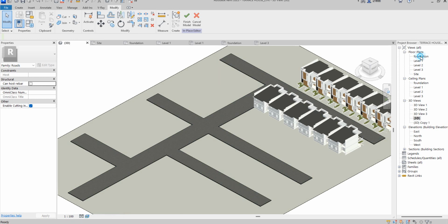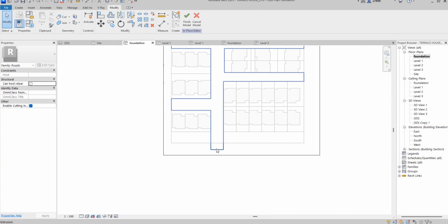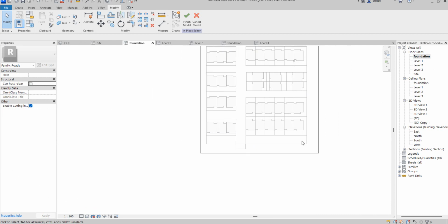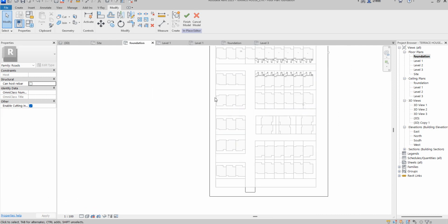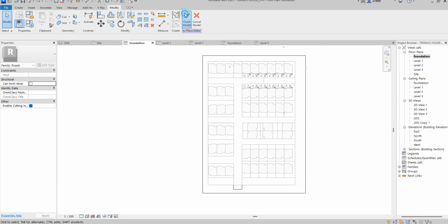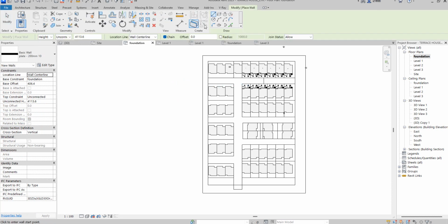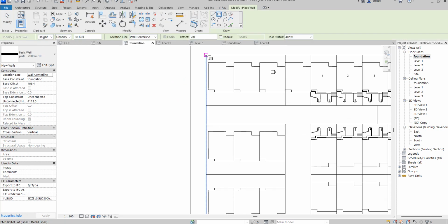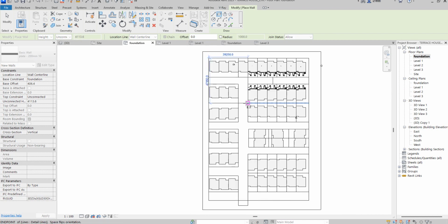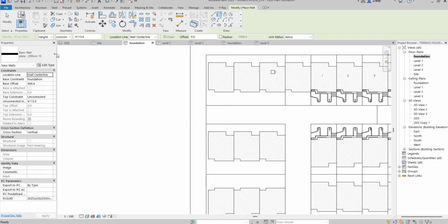So you go back to your foundation where you are programming all those things. You need to bring all the fencing to position. Let's quickly do that with just a little bit of clicking. Before we later design the gates, before we place all these things in the position where they are supposed to be, the first thing I want to do is to quickly create the fence. So click here and say wall. Just click on my rectangular option.